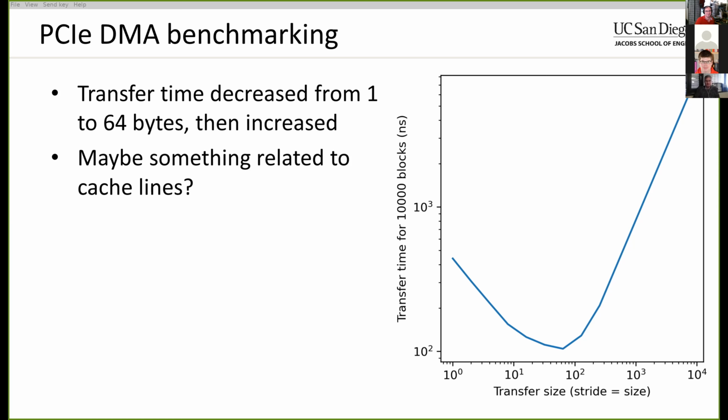Okay. And you're showing the read or the write plots? This is read. The really interesting thing is we were seeing this for both read and write, which was really perplexing. So whatever's going on here, the hypothesis that I have is that from the PCI Express side, we're not hitting CPU cache. We're probably going straight out to DRAM.